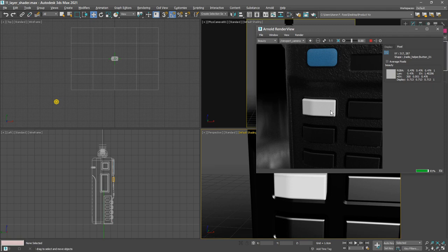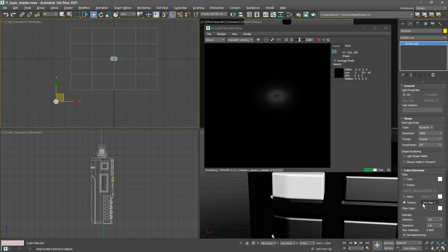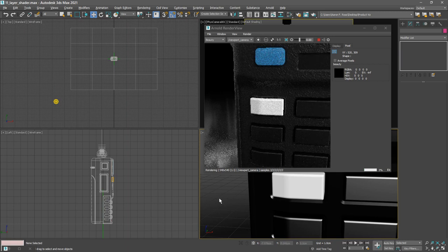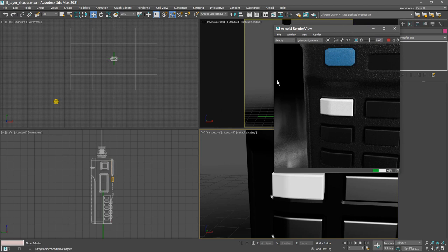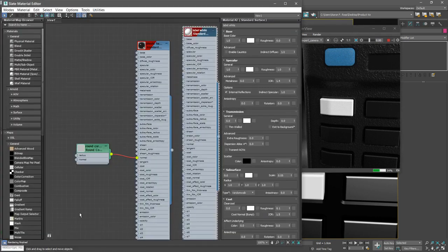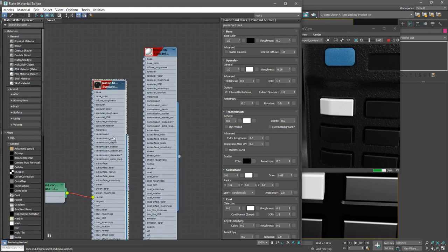So let's select that sky dome. Back in the Modify panel, we've got the color intensity rollout. Let's bring the exposure up to 2.3, and once again give focus to that perspective view. And as we move our mouse around, we're getting better exposure here. The RGB values are never going above 1. All right, so we can close that. And now we're ready to go back to our material editor. I've got that minimized. And we've got two materials here. We've got our label white and our plastic hard black. Let's bring our label white down.